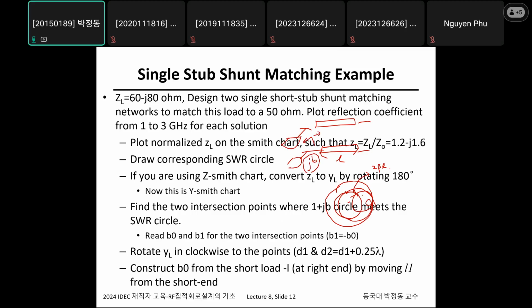Let's say the impedance seen at this point is minus jB. You just synthesize a jB to resonate out this minus jB, right? This is how we achieve it with the stub. So this is the procedure. Here we want to design GL matched to 50 ohm.